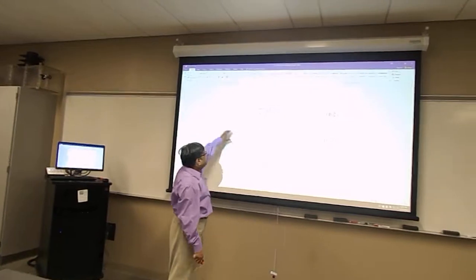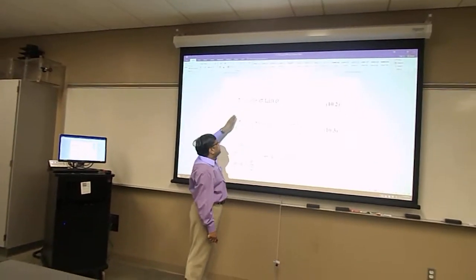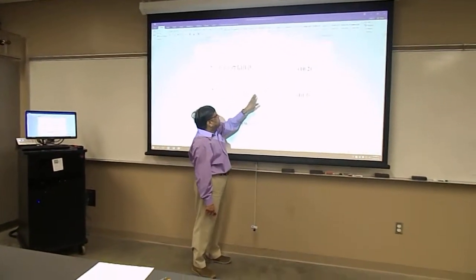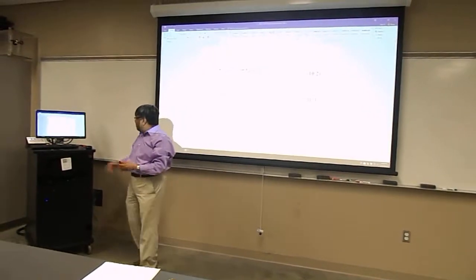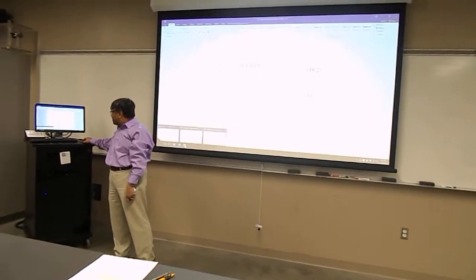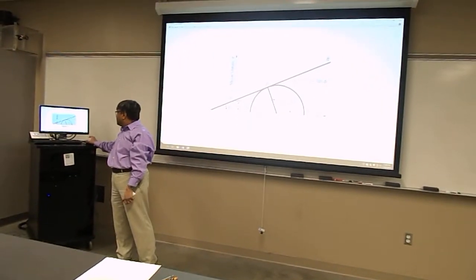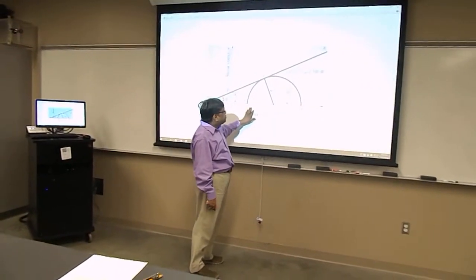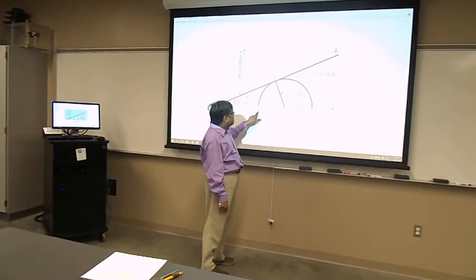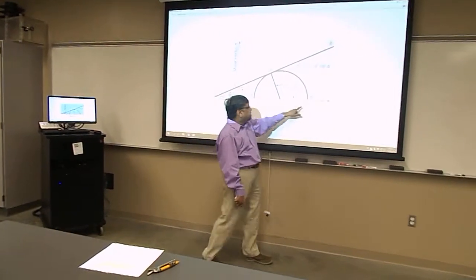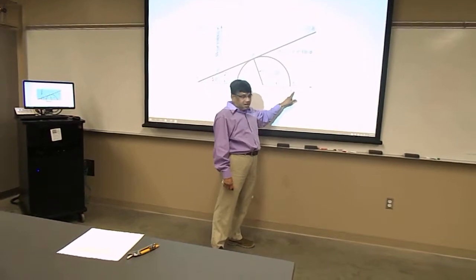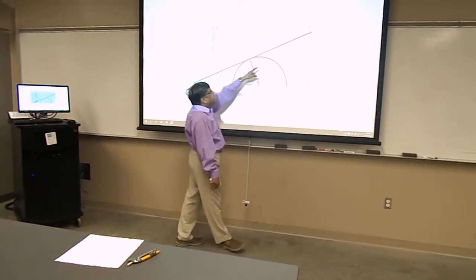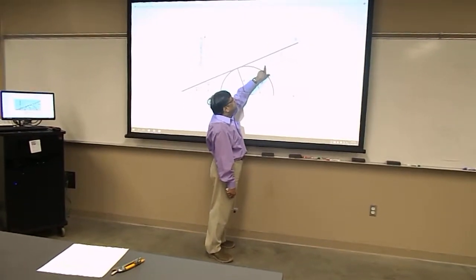Okay. To calculate the total shear strength or effective shear strength, we need these shear strength parameters C and phi, C prime and phi prime, and we can get them only from the triaxial shear strength test, triaxial shear test. Let us say we have conducted a triaxial shear test on one sample and got sigma 3 prime as sigma 3 minus u and sigma 1 prime as sigma 1 minus u. We can get C prime and phi prime to calculate the effective shear strength tau f prime.